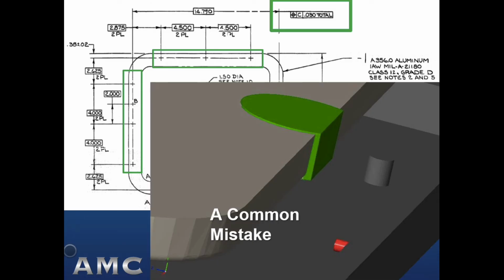Well, here's a common mistake. What we see here is solid model number 3 and that generic fixture. This is the datum C target that we talked about before, and this is the remains of the process interface geometry that was cut off. It's a stub that is ground flat by eye-hand coordination by an operator, and that stub then is ground as closely as possible to the adjacent as-cast surfaces.